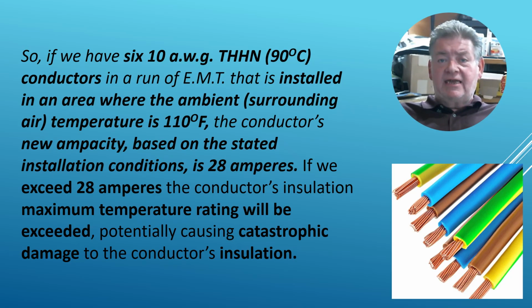If we exceed 28 amperes, the conductor's insulation's maximum temperature rating will be exceeded, potentially causing catastrophic damage to the conductor's insulation.